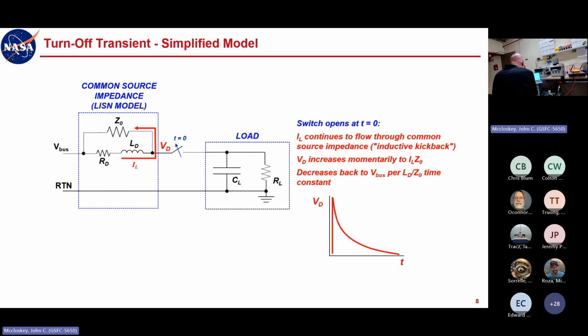You'd have to look at the power subsystem architecture to see what's the worst case that can happen on the bus when that happens. But that's how you would want to set your CS06 limits to make sure you're encompassing that properly. But I would think that you're basically just going to get a negative going transient immediately followed by a positive one.